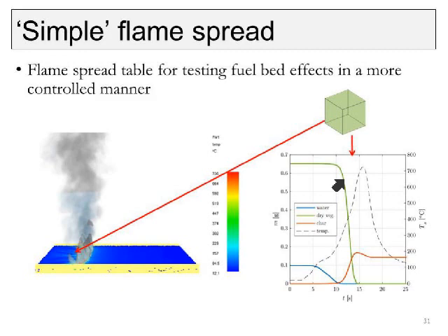And then some of this gets converted into char, and we have a little bit of a period of char oxidation here, or smoldering combustion, but we see that we produce a lot of char. We don't end up actually consuming that much. We don't have that much smoldering going on. So that already tells us, even though we don't have a direct experimental comparison, we've observed quite a lot of smoldering combustion. We already overpredicted the mass loss rate, but we're not consuming all of this char. So if we were, we ought to have even a higher mass loss rate. So maybe we do have an issue here.